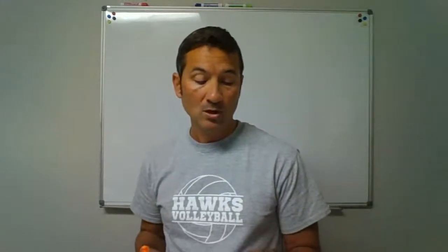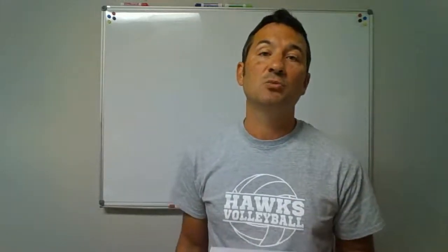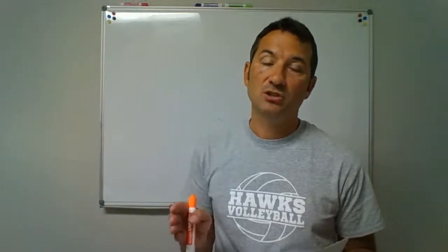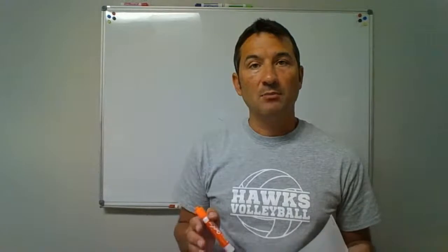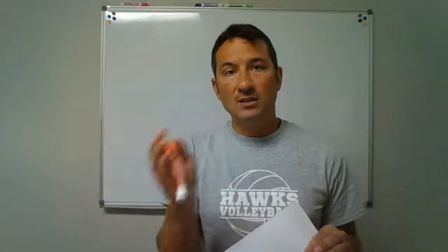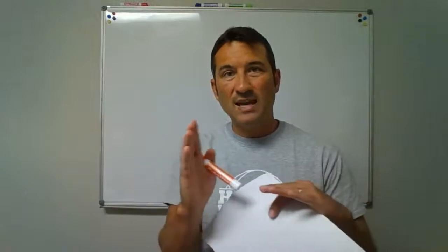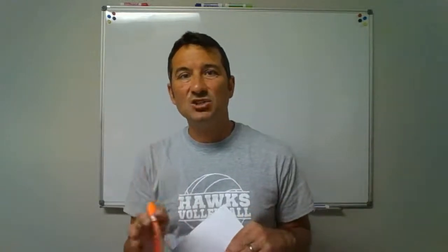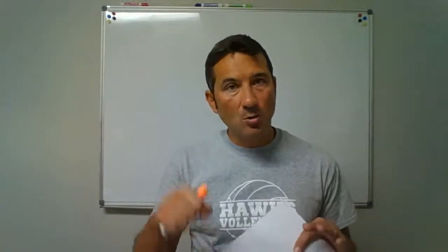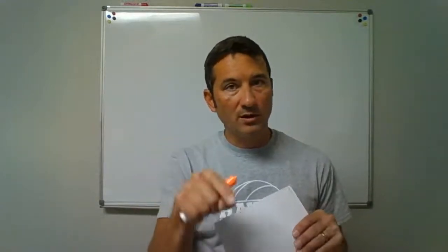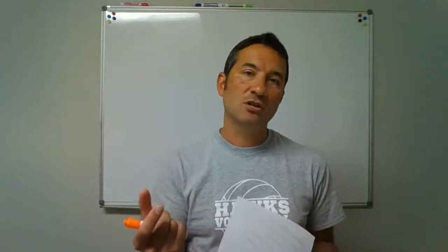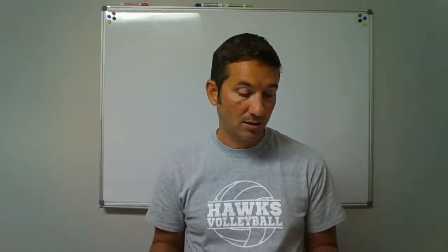Number 2, where do you need to use protective shield plates? Where have you got to put protective shield plates? If you remember, when the edge of the pipe and the edge of the framing member, when that gap between the two is less than 1.5 inches, you've got to put a protective shield plate. That drywaller comes and runs his drywall screw. We don't want it to go into your pipe. If it's over 1.5 inches, his screw's not going to be long enough to hit the pipe, so you're okay.